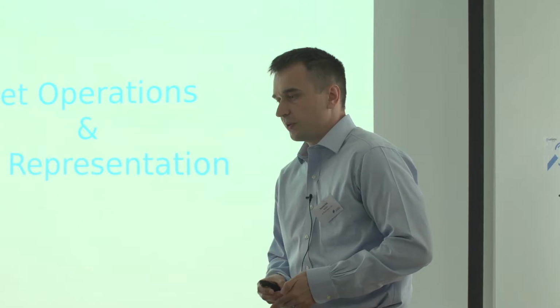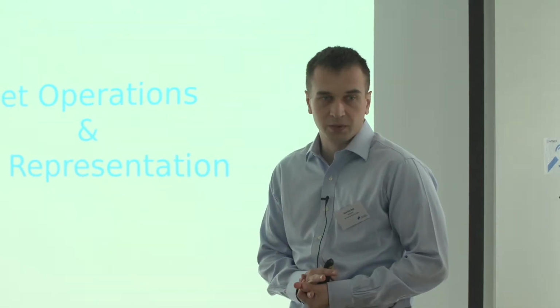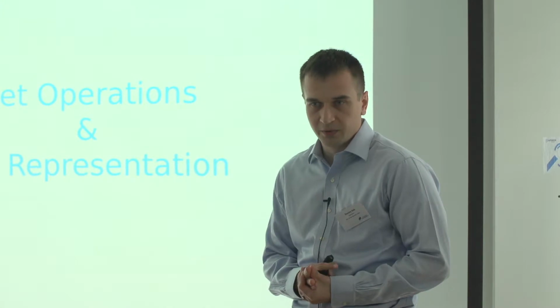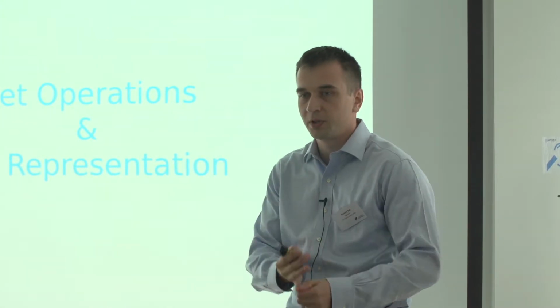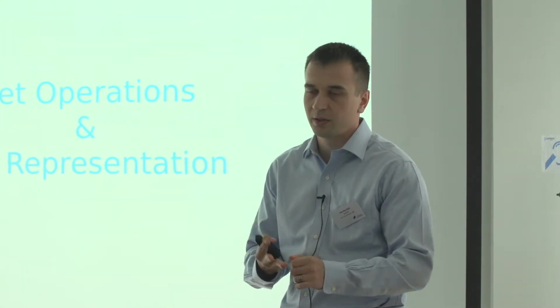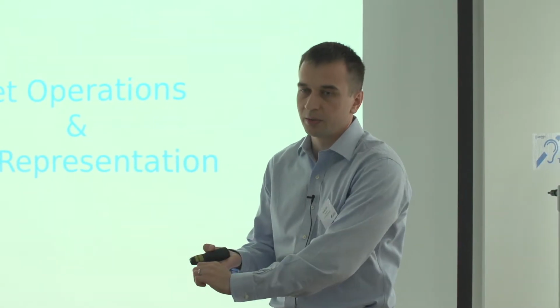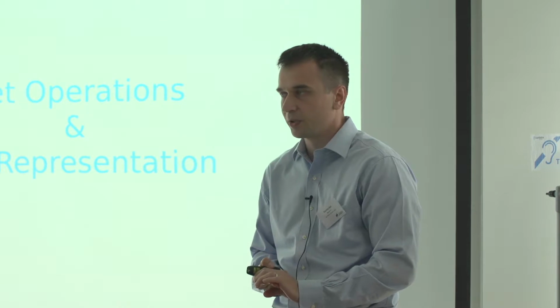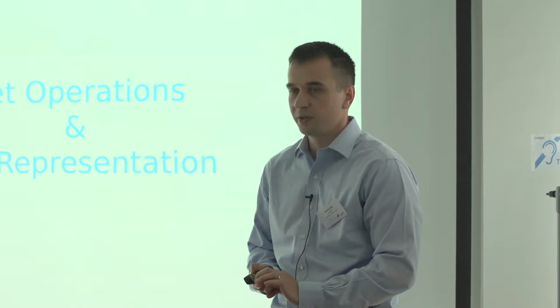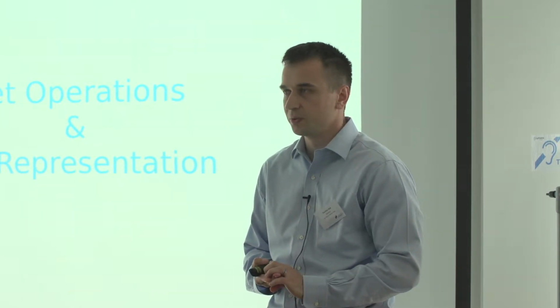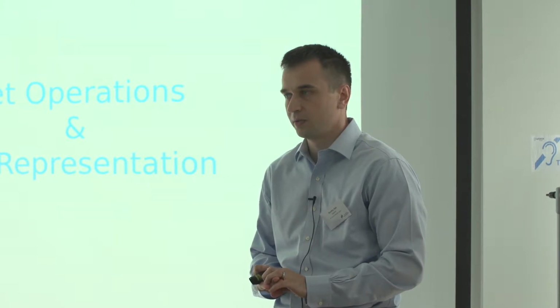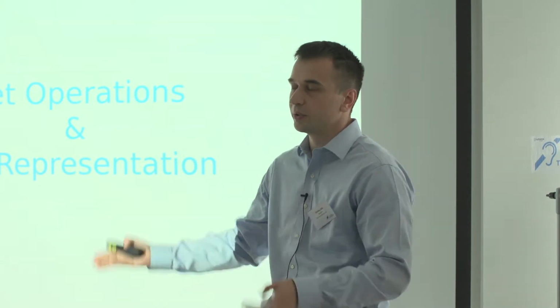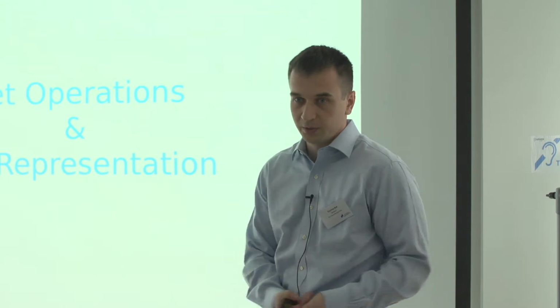I mentioned before that there are different classes of hybrid systems as well. Depending on the complexity of the continuous dynamics, you can have timed automaton, linear automaton, rectangular hybrid automaton, nonlinear hybrid automaton. The class of systems I'm going to focus on is linear hybrid automaton. Then near the end, if there's time, I'll talk about how to use methods for hybrid automata with linear ODEs on systems that have nonlinear ODEs.